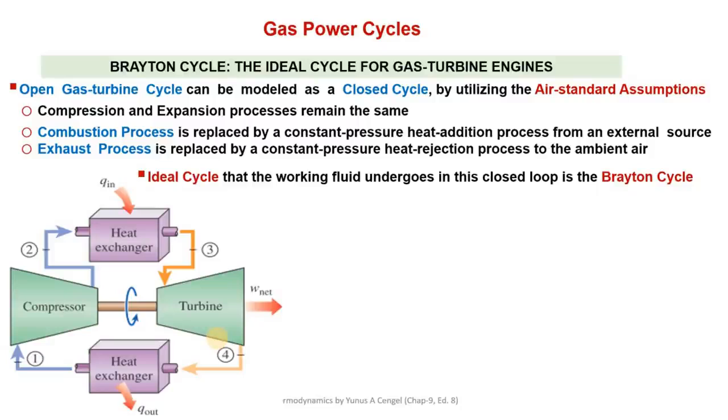And that's why the metallurgical designs of both turbines are quite different, because steam turbine blades are designed to sustain very high pressures, not very high temperatures, but gas turbines are designed to sustain very high temperatures and not pressures. Okay, these are details which are not required at this point. In some advanced course we can further discuss the metallurgical designing of these turbine blades.